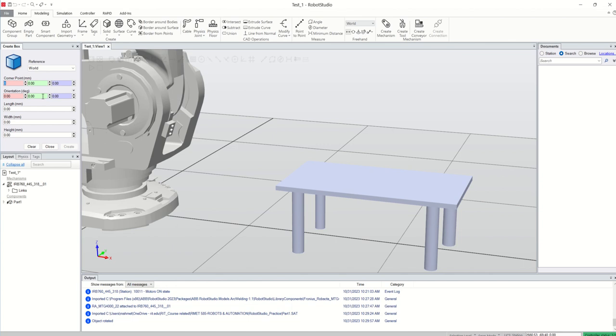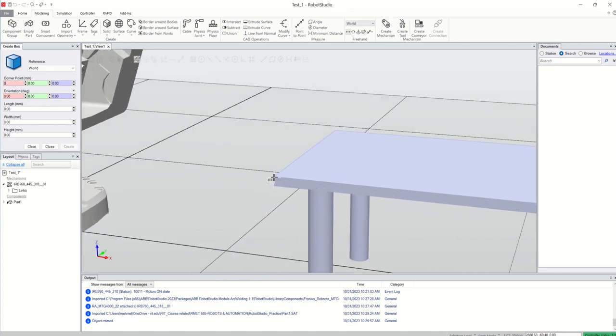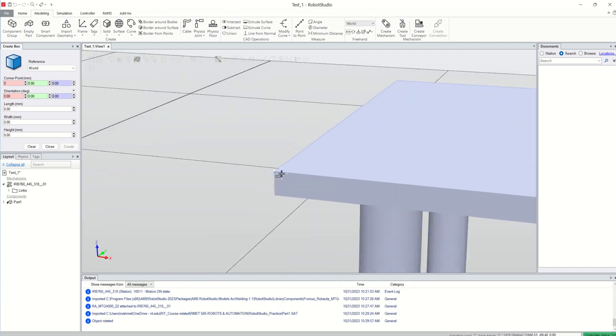If you want to draw or model a box, then you need a corner point. Maybe I'm selecting this one as the corner point, and I'm seeing nothing because I didn't select anything. First of all, you need to make sure part selection is selected, and then maybe I use the end snap. Then you go back there and click, and you will see it suggesting a point. You can select it, then you will see those numbers getting updated.